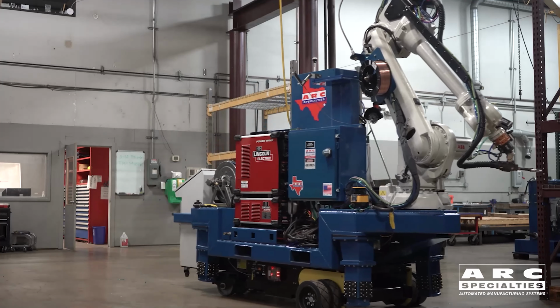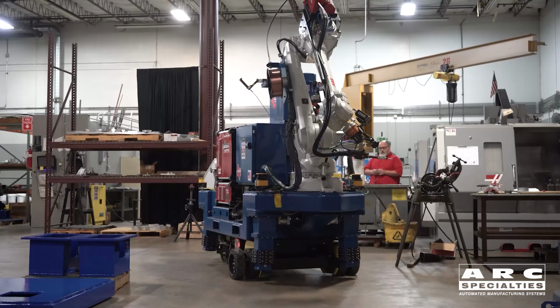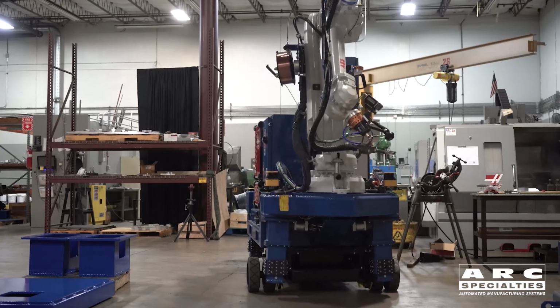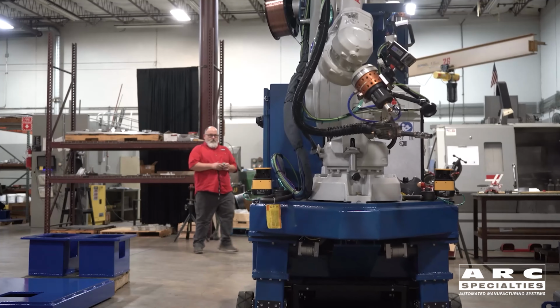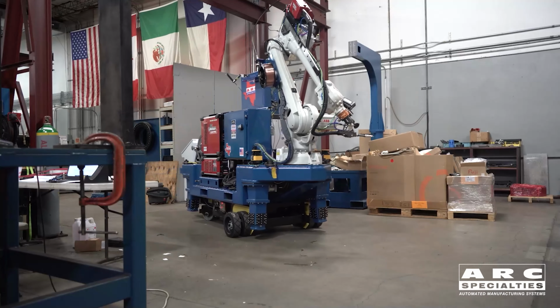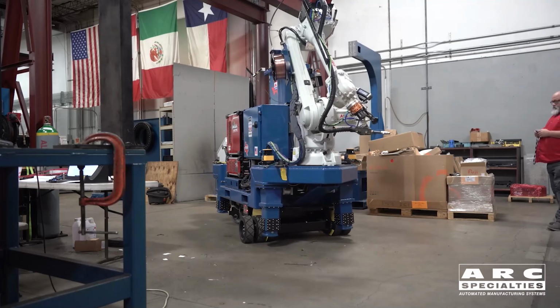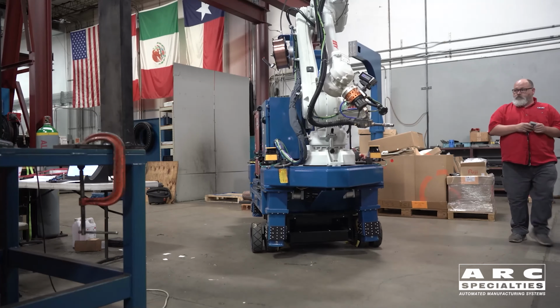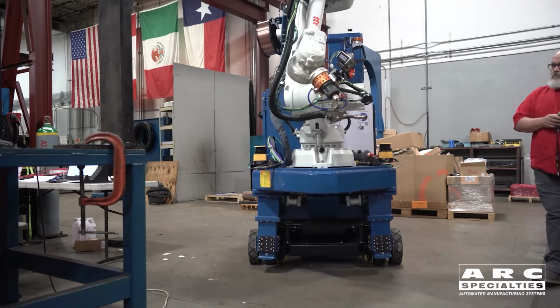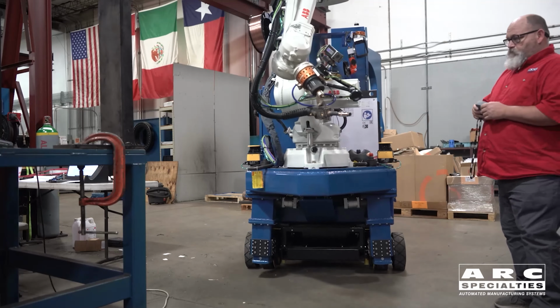The second mode of transfer is called globular. It's easily identified by large particles transferred across the arc. Each particle is actually larger than the wire itself. This only occurs at high current levels with high CO2 contents in the shielding gas. In my opinion, there are very few applications for globular transfer, but I see it being used in many factories around the world. Instead, I recommend that people go to spray transfer.